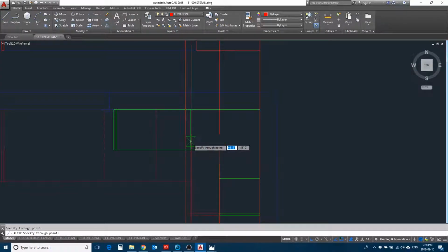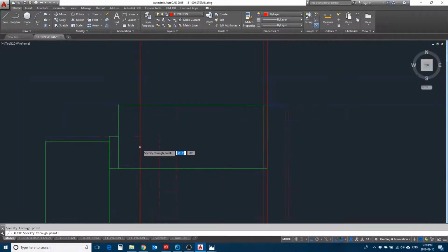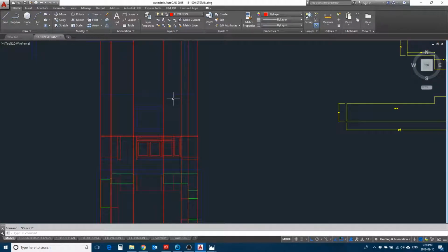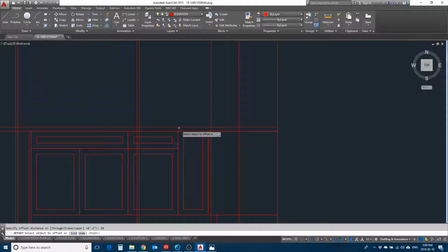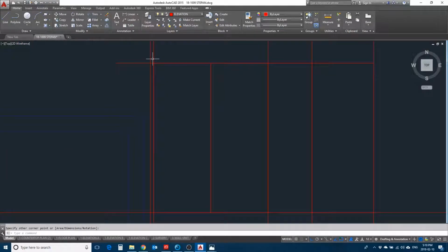Select a line. If you pressed one extra, that's okay, just do it all later. Delete the extra line that is not required. Okay, now between the countertop and the upper cabinets is 20 inches. So there we go, and we want to leave 6 inches from the ceiling, which here we cannot. Offset 6. Rectangle, so this is a door, corner cabinet, upper cabinet with 2 doors, and the finished gable.